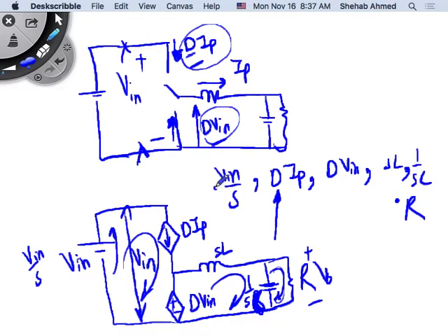Or, SL, actually we're looking at inductor current. Here you're talking about inductor current. Or here you're talking about capacitor voltage. These are the states of the circuit, right? So the states of the circuit, you're finding the voltage drop across the inductor, or the voltage drop across the capacitor in Kirchhoff voltage law. You're looking at voltage drops across the components that you have. So you're looking at voltage across the inductor or voltage across the capacitor, right? And you can relate voltage across the inductor to the current across the inductor, right? And then voltage across the capacitor is typically your state as well.